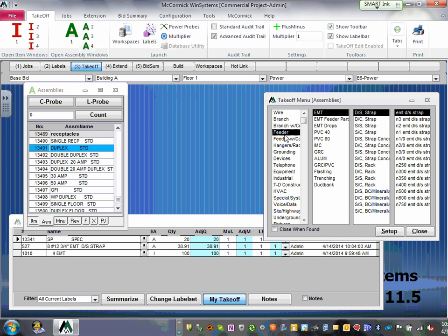Anything in the wall, MC cable, no problem. Just pick the right cable. In the ceiling, we just want to group them by how many circuits. That's all. So up to 6 circuits, right? 6 circuits, 8 conductors.